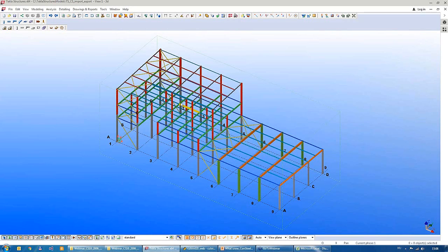The other thing is that we totally renewed the import from Tekla. Up to this time we used the Tekla output file to load the Tekla structure model in ConSteel, but this file did not contain all of the necessary information and sometimes did not work properly. So from now ConSteel 10 imports the Tekla model through the Tekla API. This way allows us to import not just the structural elements, but use the defined classes and other properties from Tekla. Let's see how it is working.